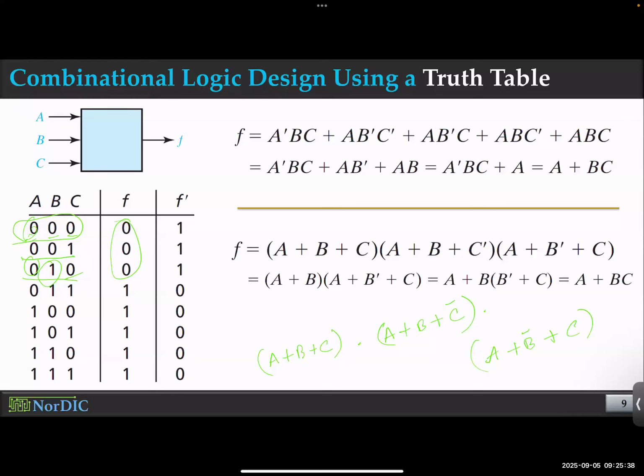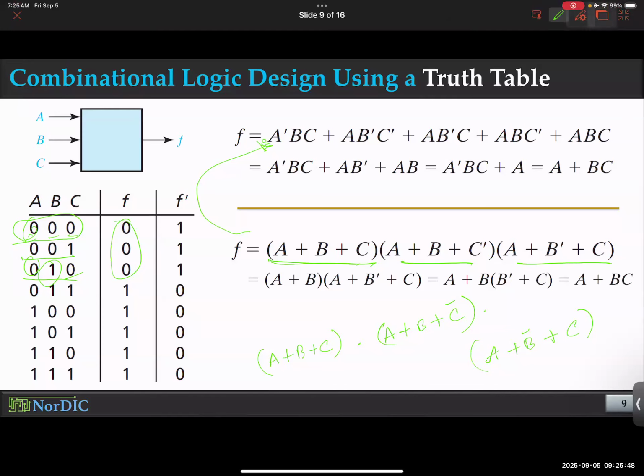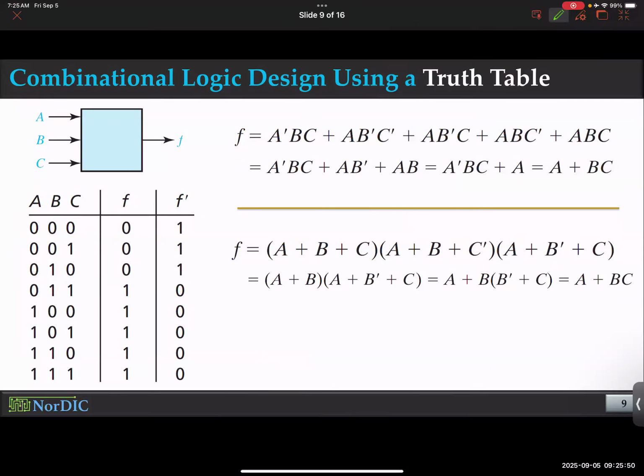Basically, this product represents AND. So this is the expression that you end up with in this approach. And obviously, it doesn't look anything similar to the one that we ended up with. However, we haven't simplified, as you can imagine. To simplify it further, we'll first have to multiply this, and then multiply this with the rest, and then simplify. So it requires even more Boolean algebra steps than you saw in the first approach.